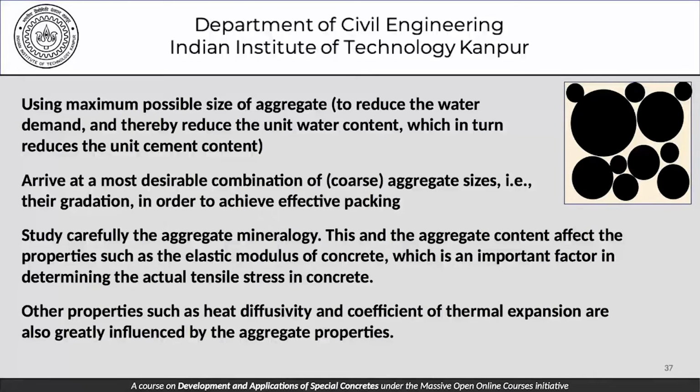Use the maximum possible size of the aggregate to reduce the water demand and thereby reduce the unit water content, which in turn reduces the unit cement content for a given water cement ratio. Arrive at a most desirable combination or a particle size distribution, their gradation, in order to achieve effective packing.